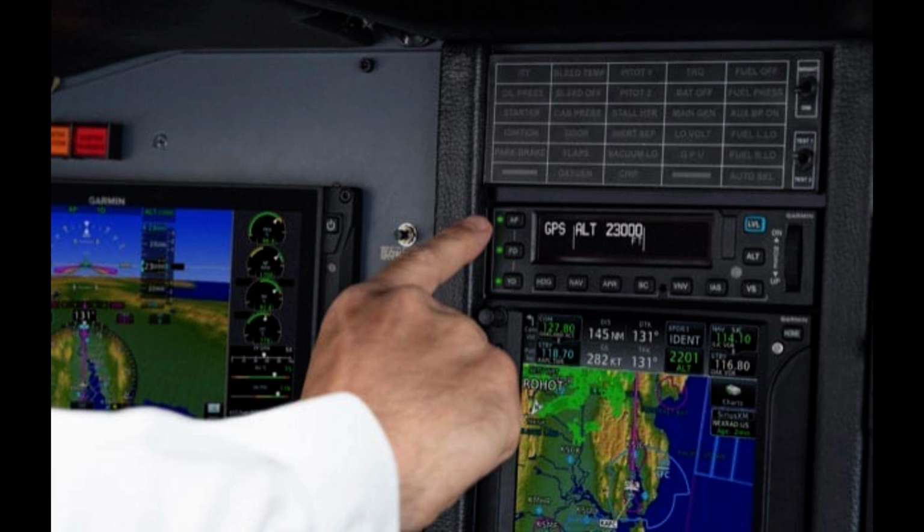The first and closest method of disconnecting a malfunctioning autopilot is the autopilot disconnect switch, typically mounted on the control yoke. This switch is usually a red button, often mistaken by new pilots for the radio transmit button. You need to know which buttons activate which functions. Most systems may be disconnected by the mode buttons on the autopilot control panel.